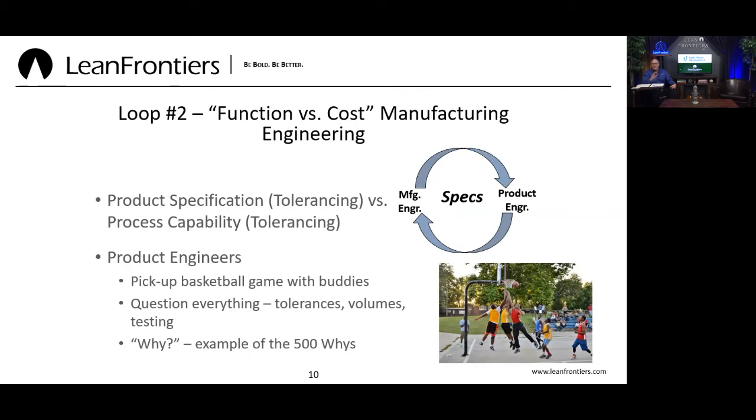But what it told me, the next question to the product engineers was, well, have we ever had any feedback from the market that this is a problem, that we have failures? And ultimately the answer was no, there weren't any failures out there in the market, which told me that we didn't necessarily need this type of tolerance. We've never produced it for 30 plus years. There was not a market failure out there, certainly due to that. So we need to reconsider it. But there were a lot of cycles. This was over several months to go through this process to try to get that tolerance changed.